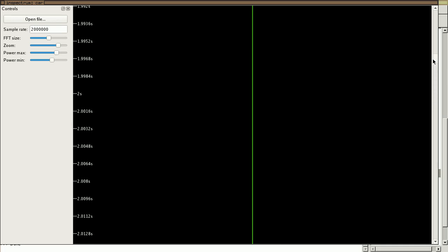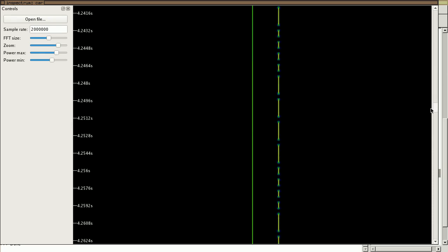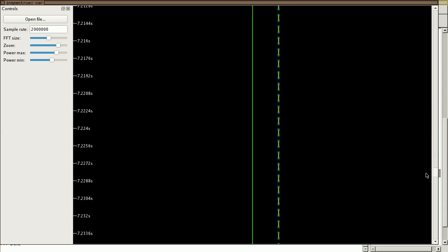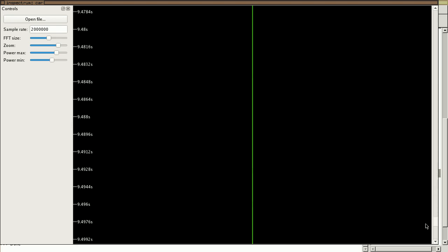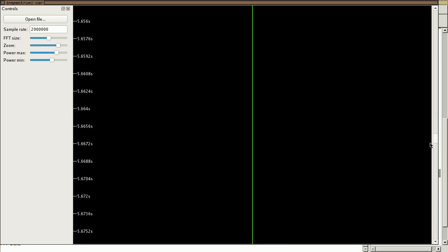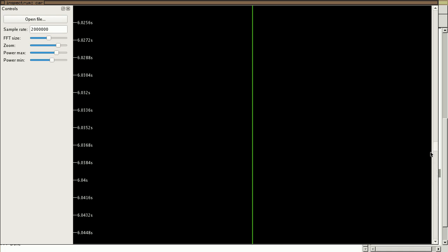If I scroll up, you can see there's a bunch of time here where nothing happens. And then I have my signal. And then there's another burst, and these probably correspond to different times that I moved the control sticks on the remote control. And then at the end, there's some empty time after I have transmitted anything. So I have some emptiness at the beginning, some emptiness at the end, and a very clear on-off keying signal right down a consistent frequency just above my center frequency.